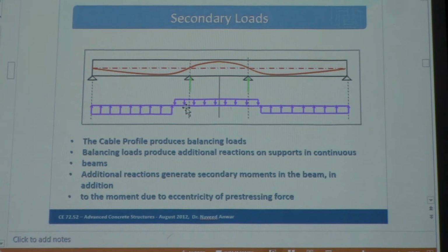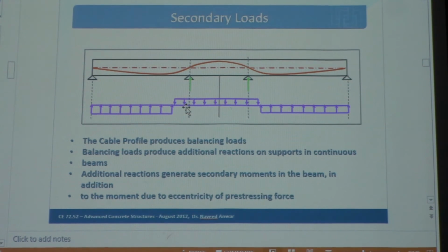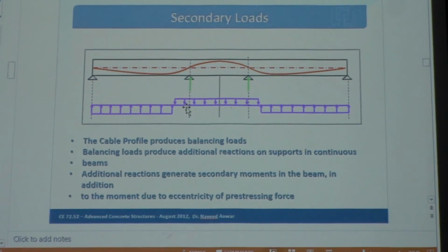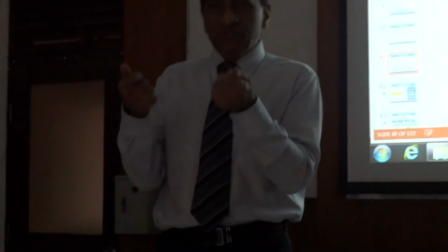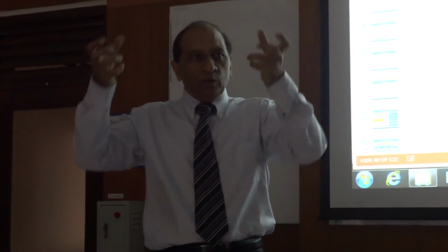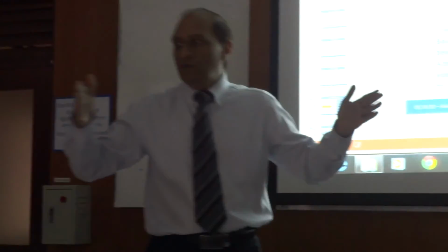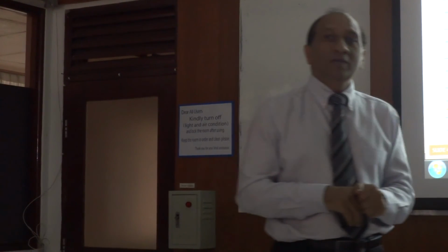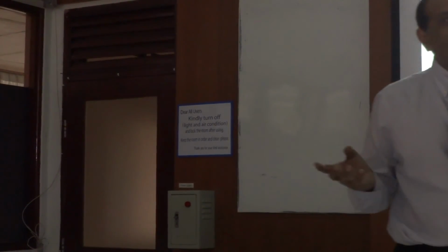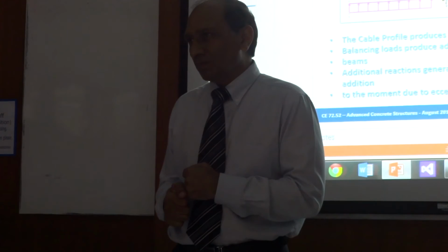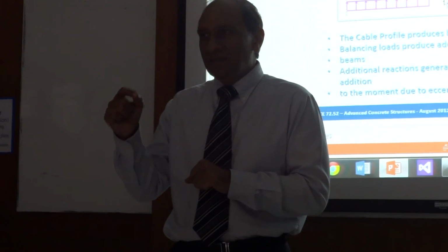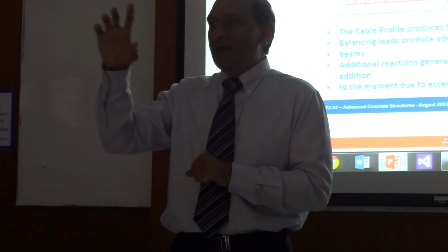The stresses that you get from the analysis are already the final results for you, because they include the effect of the bending moments from the pre-stressing, the effect of the actual loading, and the axial forces. Then you can directly use the final results to check the stresses using the stress equation, and you are done. So the design is no longer needed. It is only now a stress check, because the pre-stressing is converted into a load, and load cases can be combined.